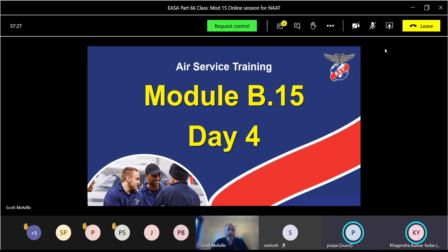Yeah, the LP spool speed, when that gets too fast, and the gas temperature, EGT. So if you get too fast or too hot, it will give an electrical signal through an amplifier. The amplifier will give the pulse to the solenoid, activate the solenoid, and that will also open a spill valve. Good. That's just a basic system.